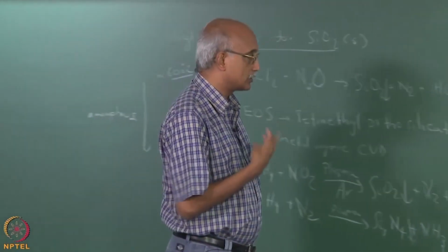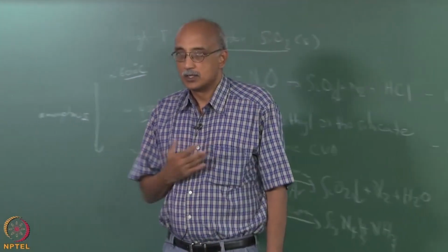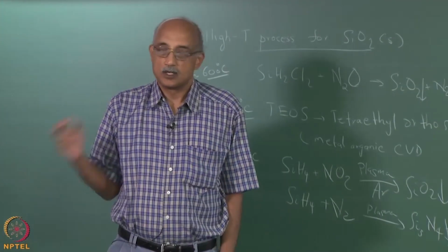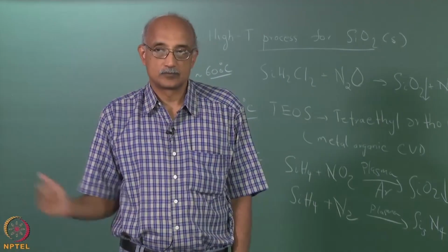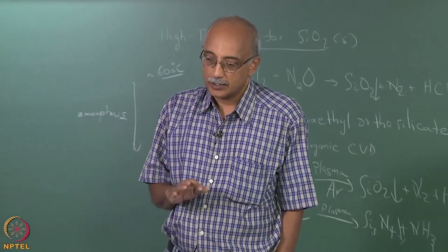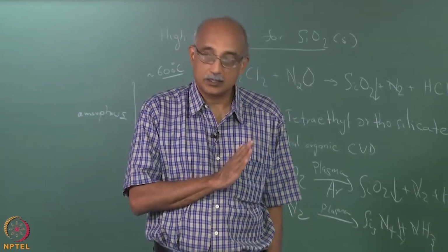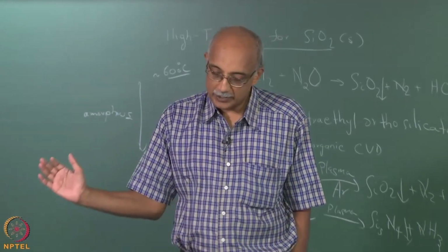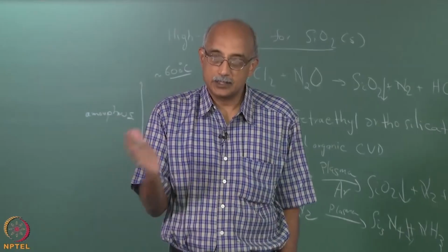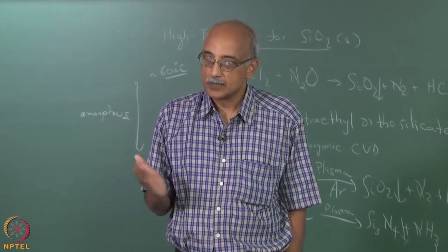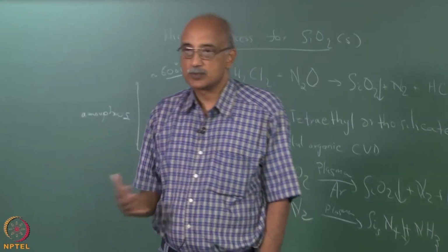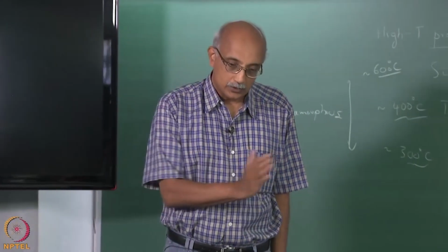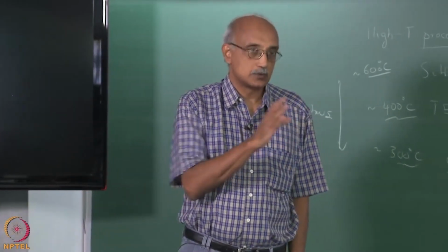And the third reason that you want to do this is to improve the flowability. Again, flowability is important for uniformity, or another way to look at it is for planarization. If you are trying to achieve a planar film of the oxide and you want it to have a planarity which is as perfect as possible, the use of these dopants enables us to make the oxide flow by heating it to say 1000 degrees centigrade and then solidifying it. So, when you use this process of inducing flow of the oxide and then resolidification, you get a very uniform film if you use either of these dopants.